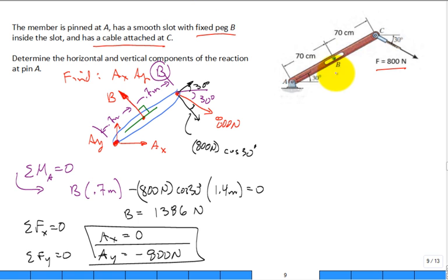This member has only a force at B, a force at A, and a force at C. This is a 3-force member. When you get good at identifying 2-force members, you'll look for them because you'll know they're either just tension or compression along the line of the pin connections on the ends. But 3-force members are a little different.